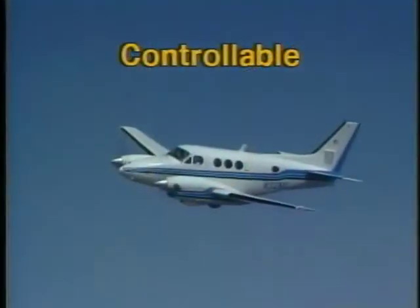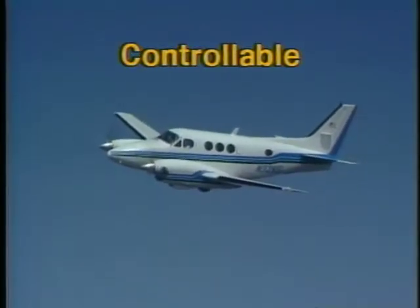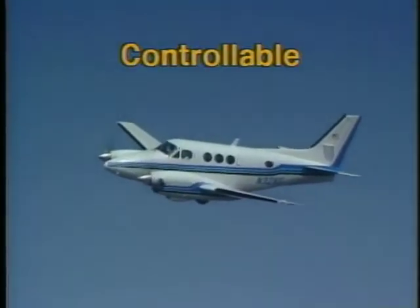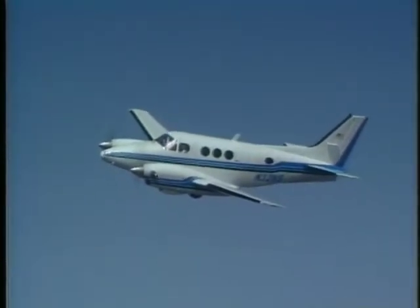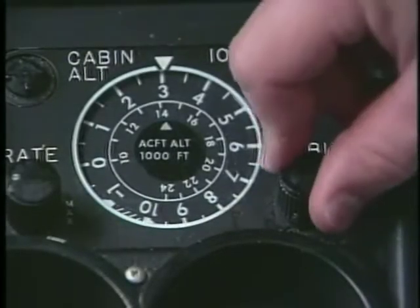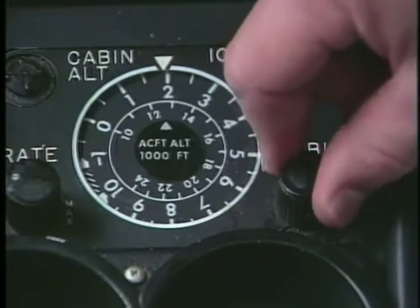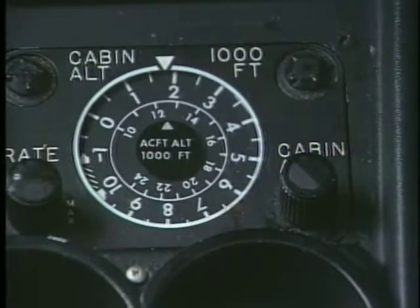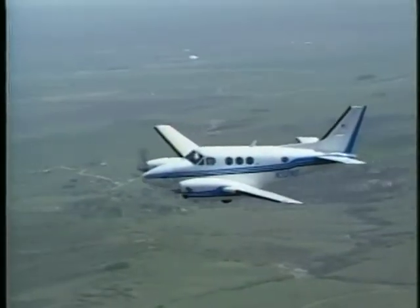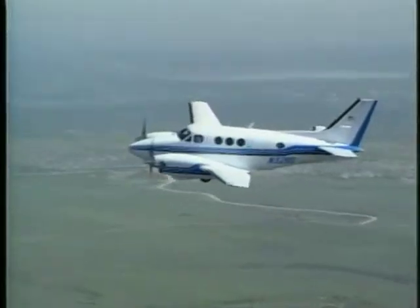A controllable system is more complex, but it allows flexibility and control that the basic system lacks. With a controllable system, the pilot can choose where pressurization begins. For instance, you can begin pressurizing the cabin at pattern altitude, and the cabin remains at that altitude until it reaches the maximum allowable pressure differential. Then, the outflow valve maintains this pressure differential as the aircraft climbs.